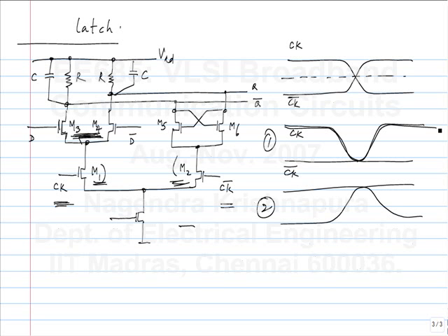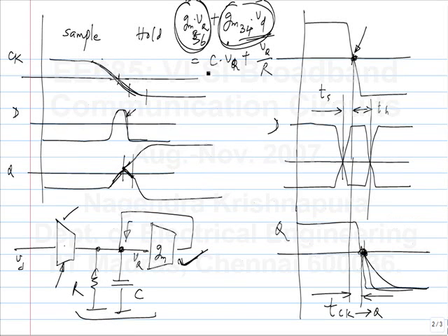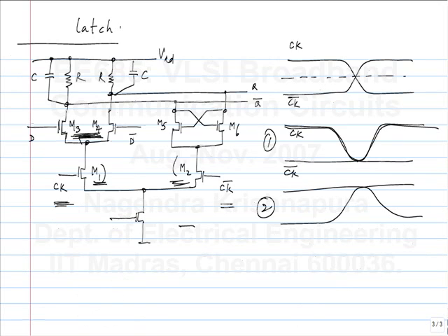Let's say it's able to hold it for that much period. They both are off, because then there is no instant of time during which both differential pairs are affecting the output. That's the bottom line. So I had written this GM56 VQ plus GM34 VD. What he is saying is this will never happen. It's either the first term or the second term. Is this correct? It is correct.